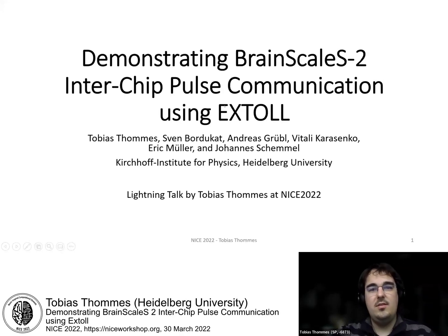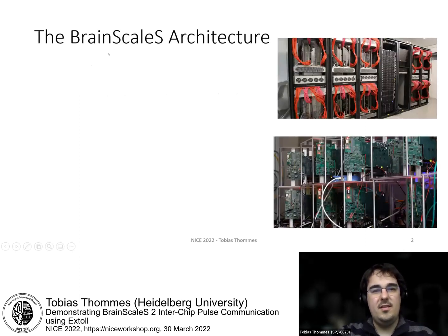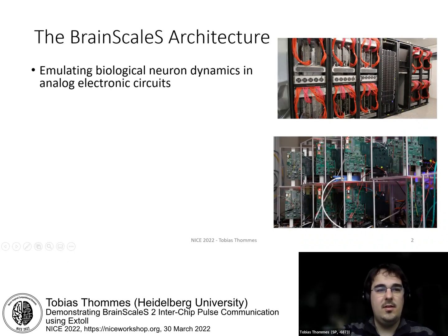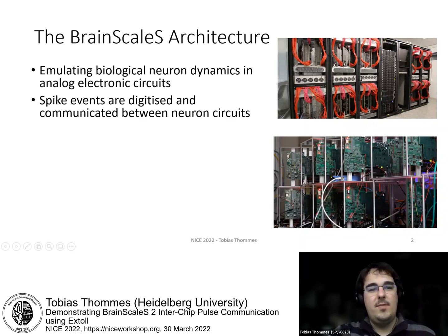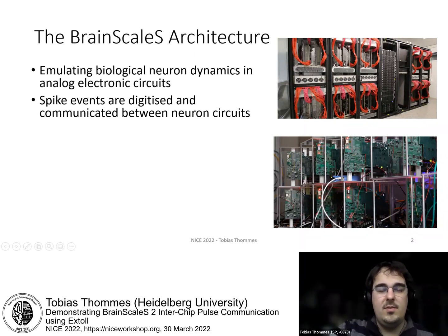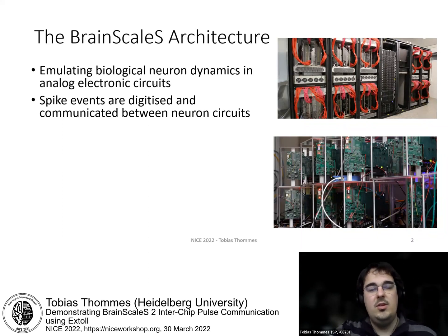Today I want to present to you the demonstration of BrainScaleS 2 interchip pulse communication using the EXTOLL network, and briefly summarize the BrainScaleS architecture. So we are emulating biological neuron dynamics in analog electronic circuits, and spike events are digitized from these analog circuits and communicated between neuron circuits.